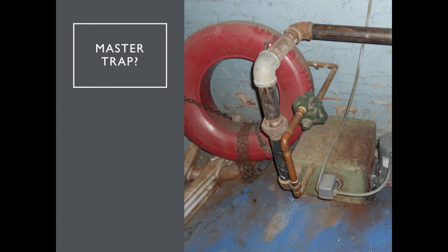Okay, and Peter is wondering, how often should we drain the boiler and refill? Never. I don't like to do that at all, because every time you drain your boiler, you're bringing in oxygen, you're bringing in hardness and scale. What I like to do is limit how much water your system is making up.